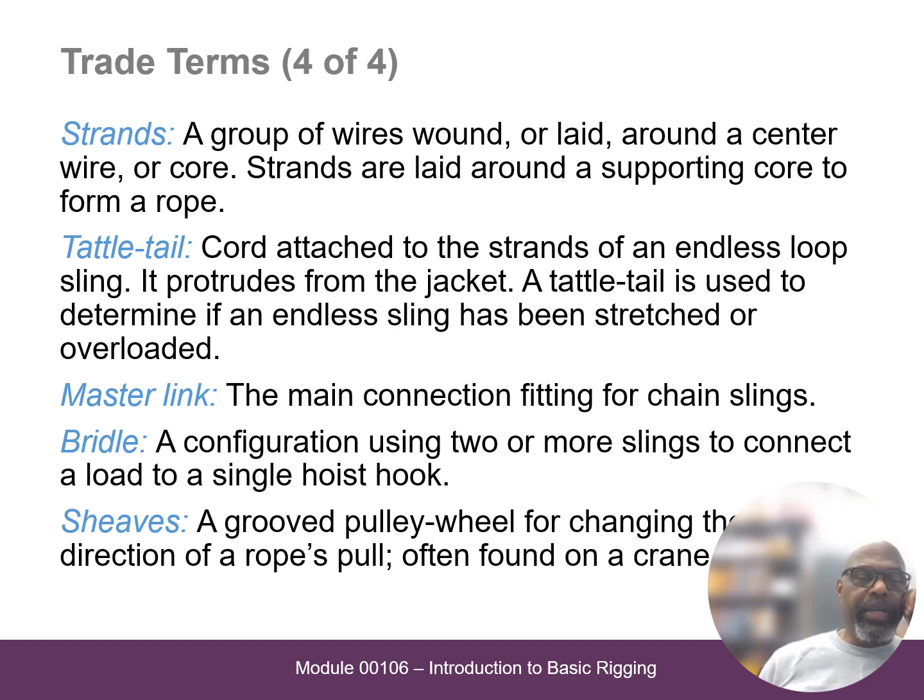Basically, they put a special strand of wire or string inside of a cable or a rope, and if it has been stretched out, the telltales would stick out and protrude. So you can tell, oh, this line is damaged. We cannot use it any longer because the telltales have released themselves. I will show a picture of it so you know what it is.